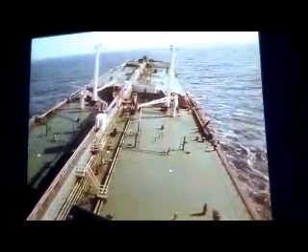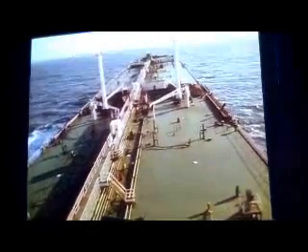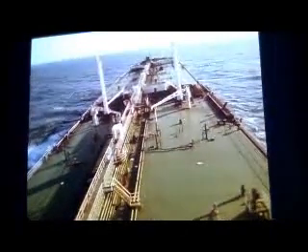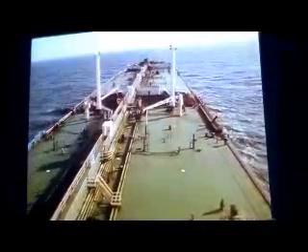In calm weather, the drift motion of a ship in deep open seas has the speed and direction of the current. But in rougher weather, waves also cause a ship to drift by momentum imparted from the waves as they are reflected off the vessel. Both the frequency of encounter and the roll period of the vessel can alter the effectiveness of this transfer of momentum.